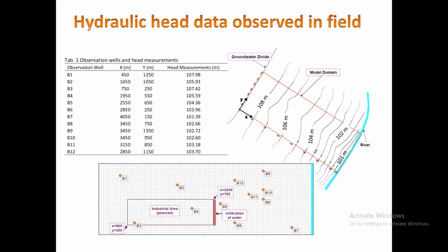Explain how we would know, for example, that this model is a good model or a bad model. And yes, you said it has to match your observation in the field. So basically, this is the most basic concept. I have an initial conceptualization of my model. Here, I define my hydraulic conductivity field, I define my boundary condition, I run my model, and it will simulate a head.